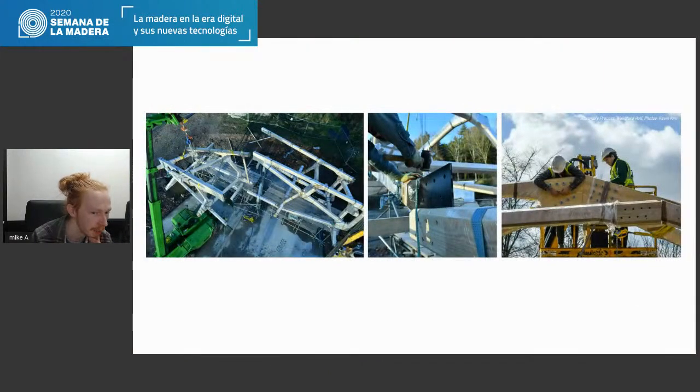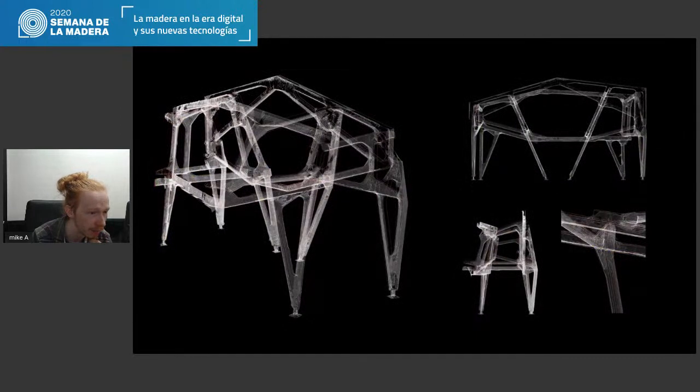So then we came to assembly, which fortunately came together very well and very smoothly. We were able to position all these frames together and bring them into site and achieve these really tight joints that were required for the system to work. And we then verified all this data using those initial reference markers and LiDAR scanning to see how close this was in general. And we found that the structure matched within 5 millimeters within a 6 meter span. So over the entire height of the building, there's about 5 millimeters of error.